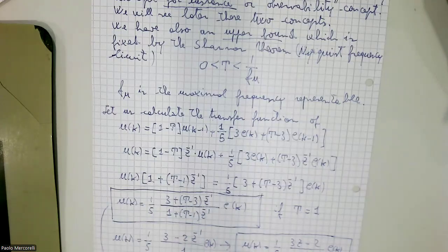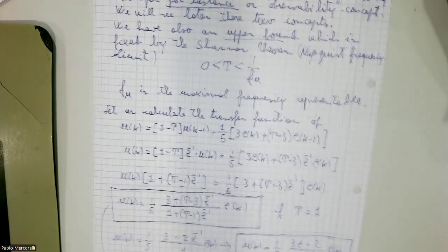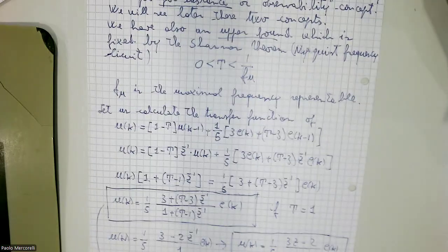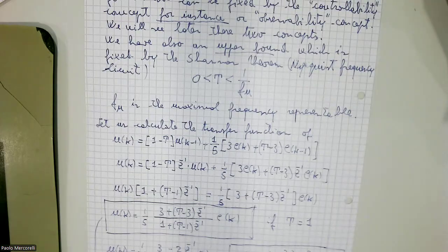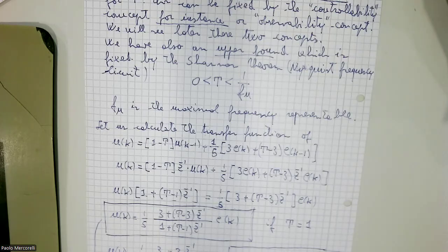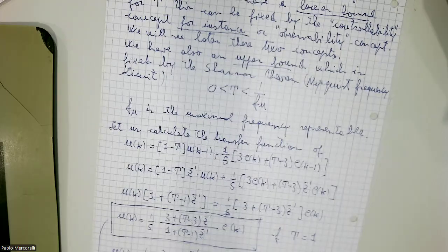We had also before, even though I didn't emphasize it, poles and zeros characterize the dynamics of the discrete controller. We can see a denominator and numerator. This is the idea: I can design the controller considering where I will place the poles, the solution of the denominator, and where I place the zero.